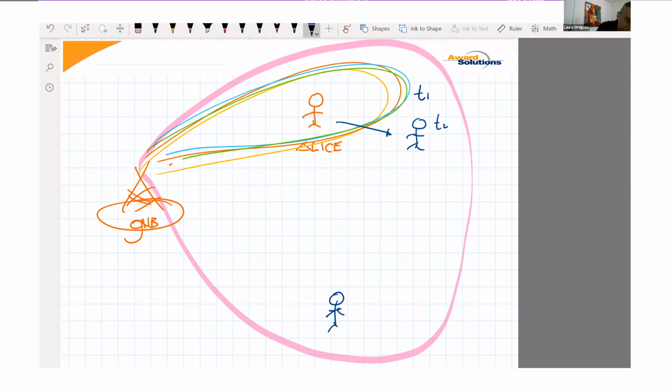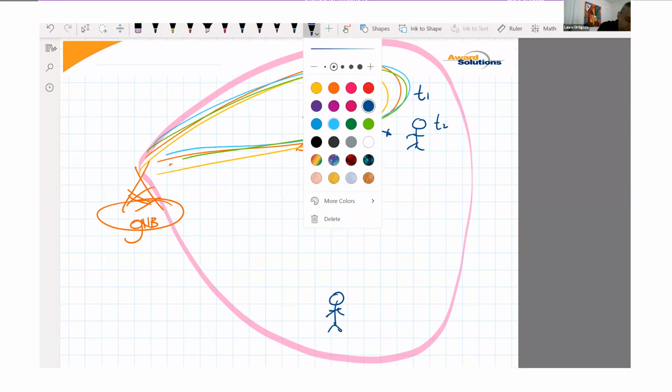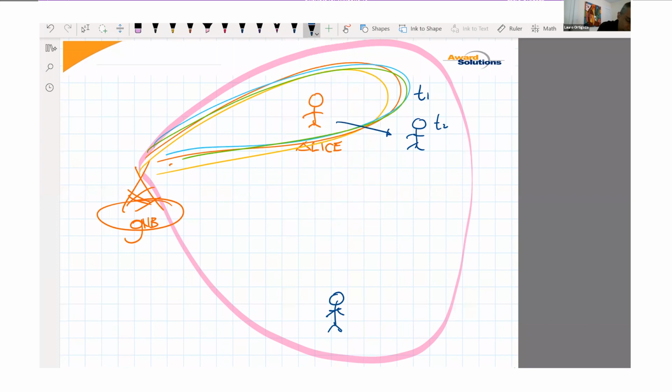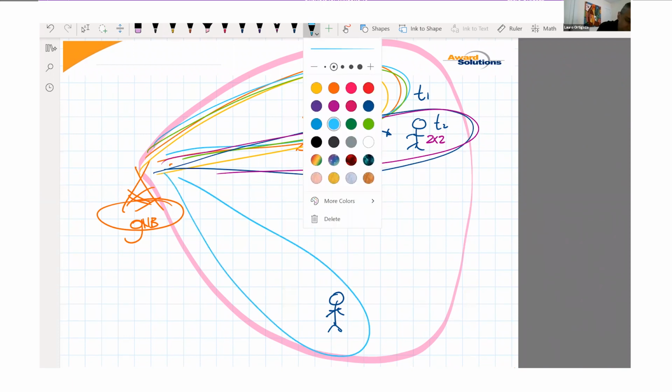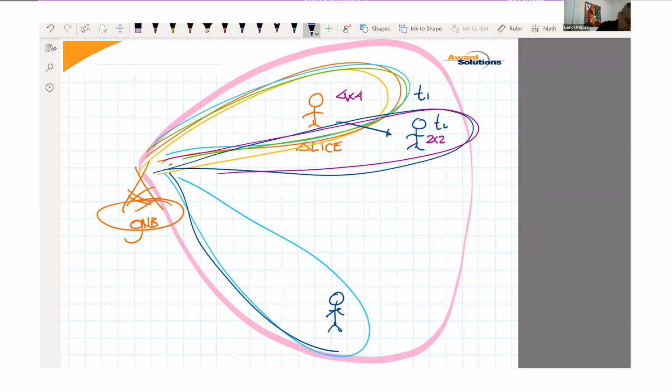So this is another example of what I was telling you, right, guys? Here, this is not cross-polarized. This is just one single beam. So here we have 8 subarrays. How many beams are we going to produce? 8. How many layers? 1 layer each of them. Remember, 1 layer each of them. Now I can also divide this into 4 beams, 4 subarrays.